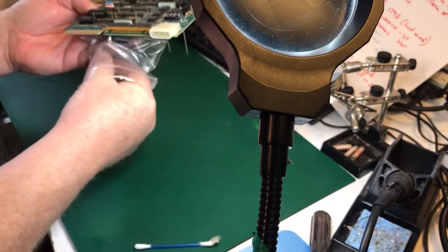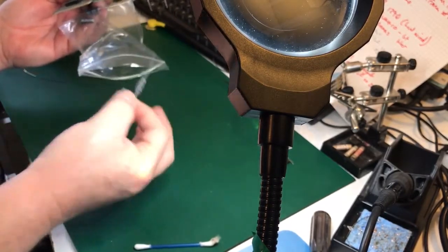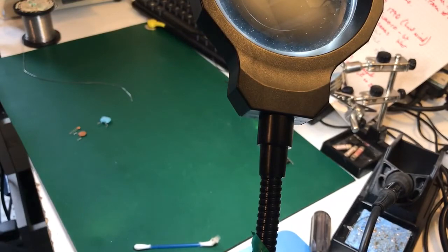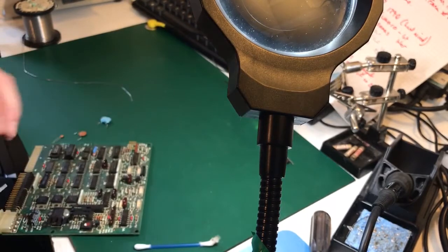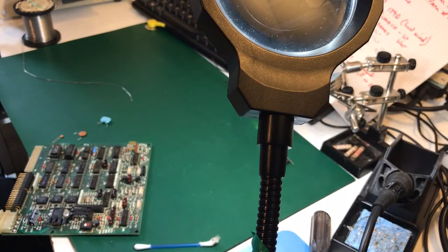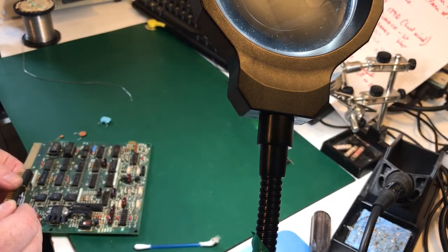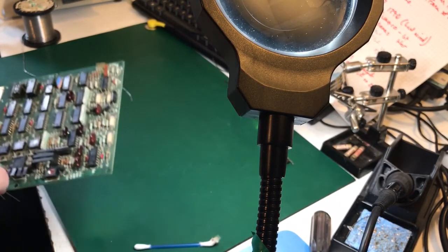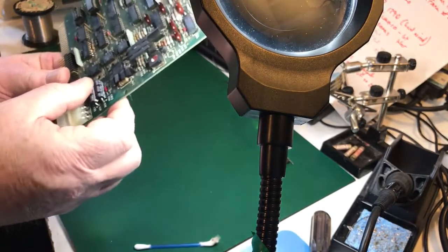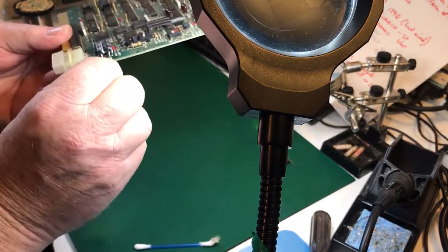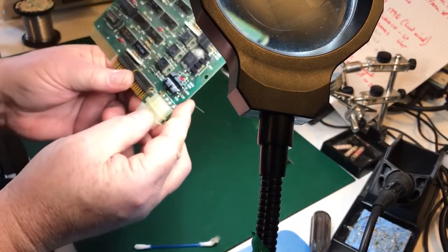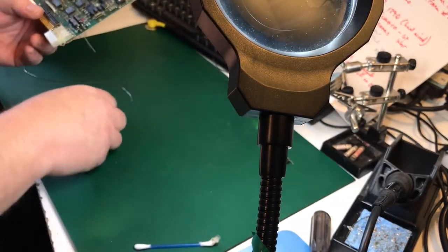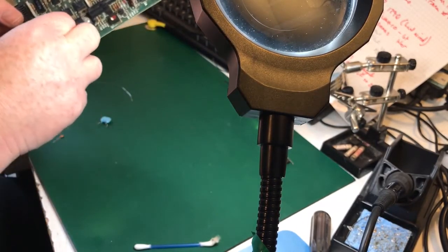Get some more of these. Obviously I got quite a few from recap spectrums and things. Okie dokie. So we do the same with this one. I think that we will make it so the neg stripe is a little bit less visible, but you can still see the value. No point in putting the old cap back. Well, I think they fit. All right, there. Look at that. That's just about right. And 25 volt will be fine. It's a little bit higher rating than the original. Yep, that's fine. And like I said, we'll probably put the ceramic in instead of what was the charred one.